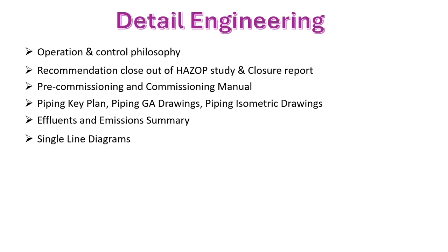That needs to be prepared through the single line diagram for the site execution team. Then the instrumentation loop diagram needs to be reviewed and released for the actual execution, like which JB contains how many instruments, its IOs, and JB finalization according to this.